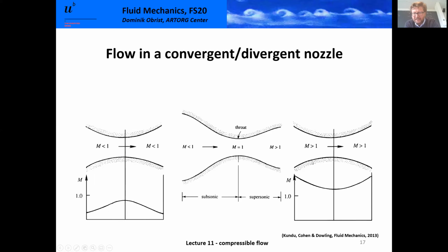On the opposite, we can start with supersonic flow and end with supersonic flow, and it's the same, just the opposite, because in the converging nozzle the velocity is decreasing, but it's still supersonic at the throat, and we can go up on the other side again. The interesting case is this here,